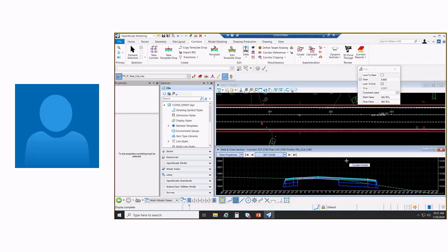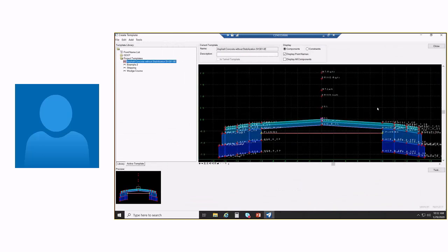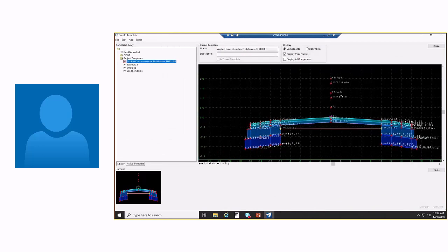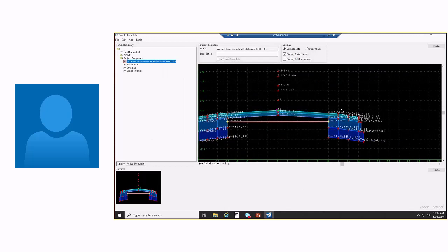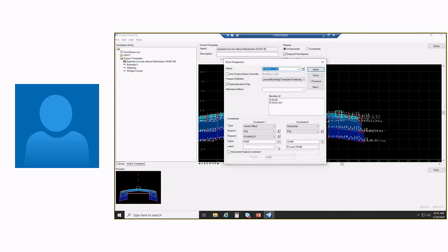Okay. And then come back to the processing-wise, if the lane's longer than your transition, then you might just do the lane width in your template, have it draw the extra lane, and then just have the constraint just to taper it back. So your constraint is just that taper length. So processing-wise, you're saving yourself too. But either way works. I would assume most people might gravitate towards setting their width in the template and then tapering back in. But either way works. So I'll just change this to 24.